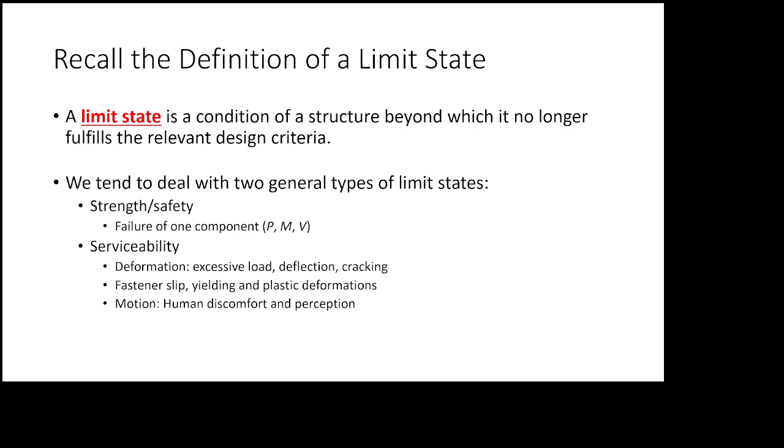But it is worth mentioning that there are also a host of other limit states that have nothing to do with whether or not the structure is going to fall down and kill somebody. They have to do with whether or not the structure is performing its day-to-day intended functions. We call those service limit states.